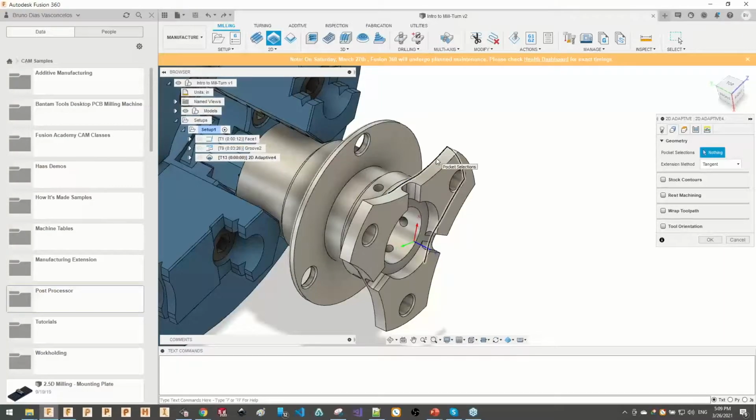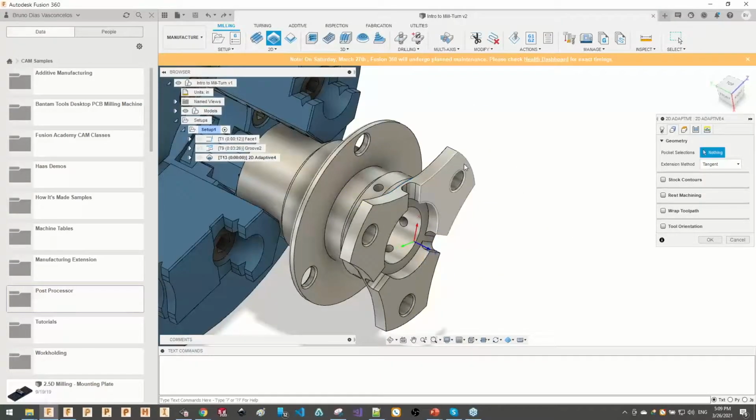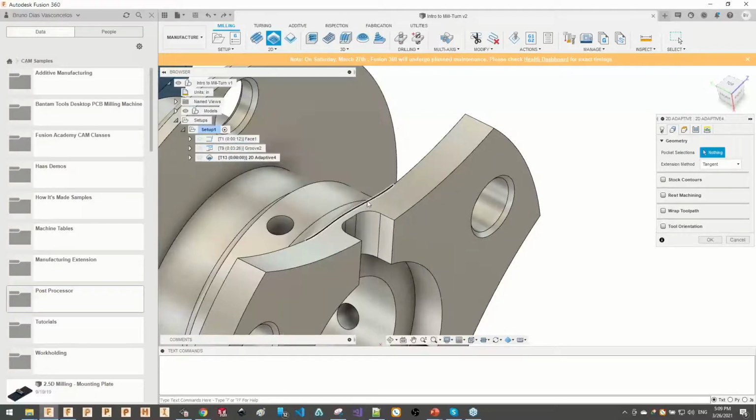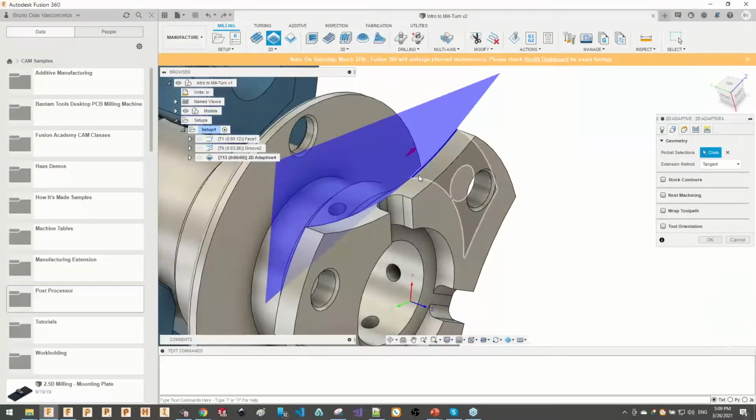Another thing, let's suppose that I don't want to propagate my selection like it is doing right now. So what can I do to not propagate the selection? I would like to select only the top edge, only this edge. So what you need to do is hold down Alt on your keyboard, keep it pressed, hover the mouse, and you will see now it is not propagating anything. You see that? I'm selecting single edges. So I'm going to hold down Alt, hover the mouse, click there, and now it starts getting shape. Let me click again.